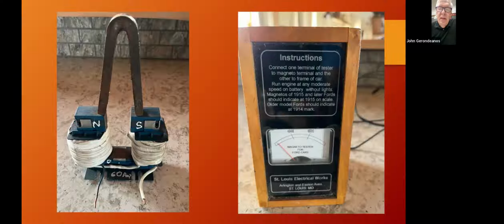And the second piece of kit that we're showing here is related to the whole issue of the magneto alternator in a Ford Model T. This is something that Kevin built, and it's a meter that you put on your magneto terminal to ground. And if you spin your car up without the magnets in it and the wheels off the ground, you'll get a reading on there. It's calibrated for the early magnetos and the later magnetos. Next picture, please.